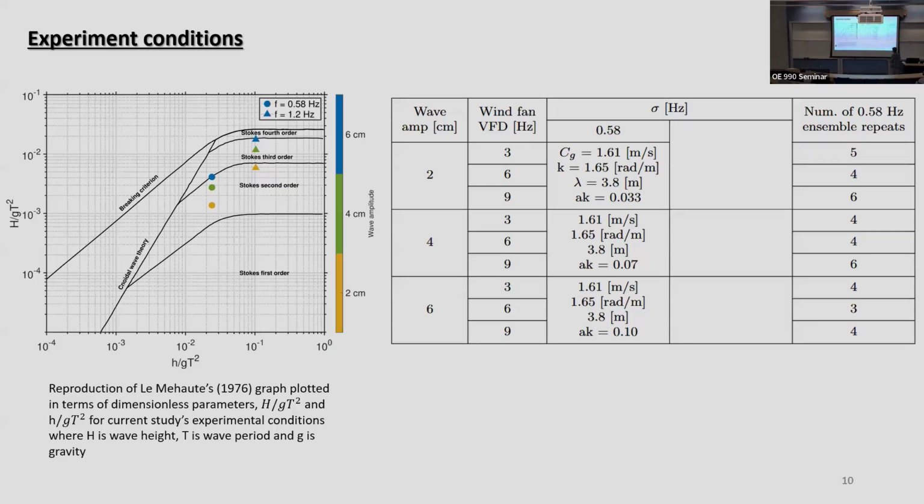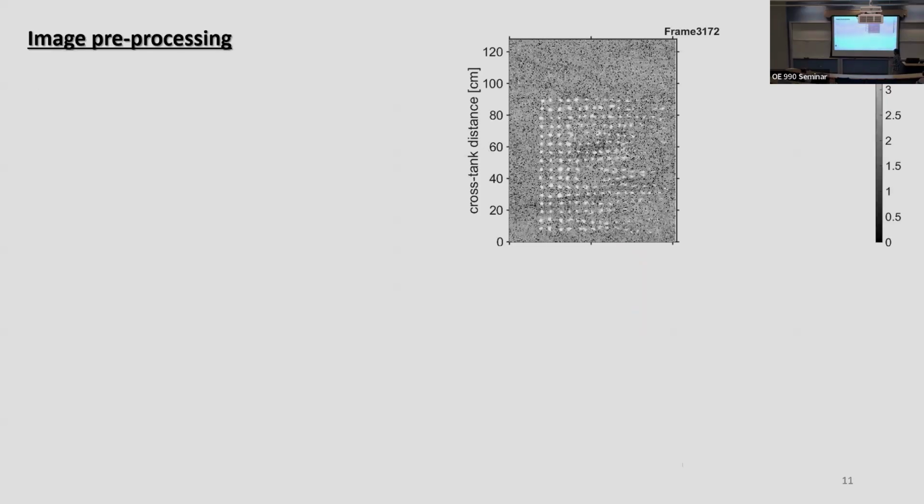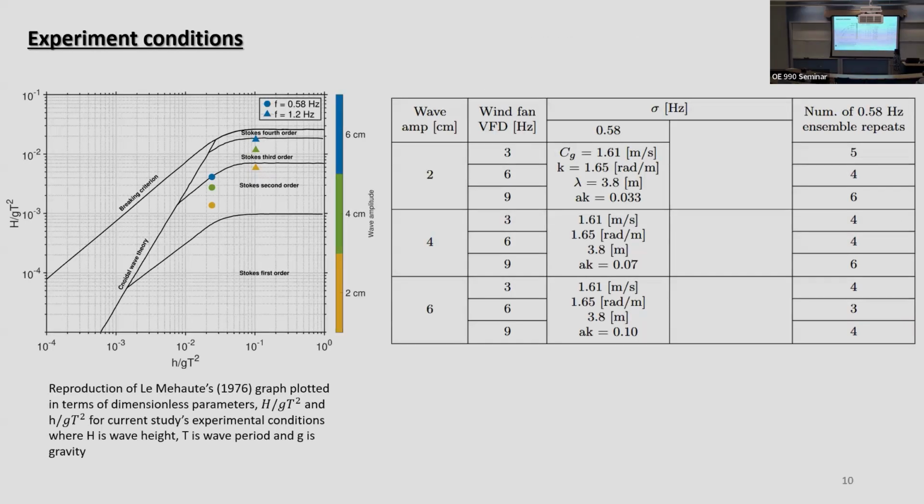They edge right around a third order correction, which will be required for the Stokes wave solution. We do that by considering the third order Stokes wave solution. So just to maintain uniformity and to incorporate all these conditions, we used a third order solution whenever we construct a theoretical solution from here onwards.